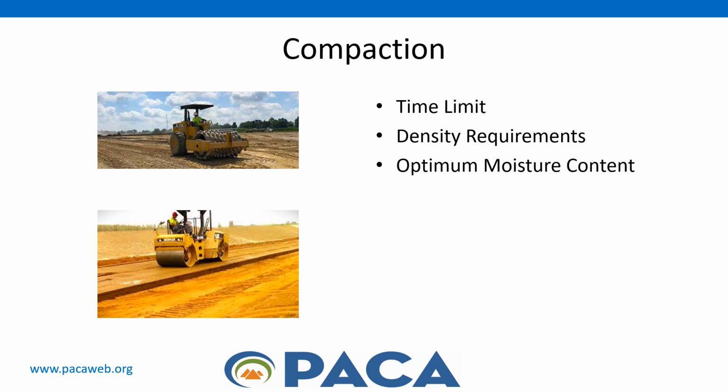The process continues. The next step in the cement soil stabilization process is compaction. The time limit between mixing and compacting is not as stringent for the soil cement stabilization process as it is for the cement treated base. Although, if possible, compaction should occur immediately after mixing, and all cement soil stabilization construction operations should be completed on the same day. Each compacted lift should meet the density requirements and the optimum moisture content requirements stated in the geotechnical report or any applicable specifications.